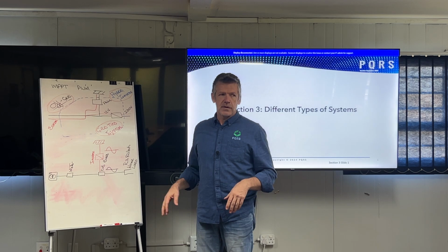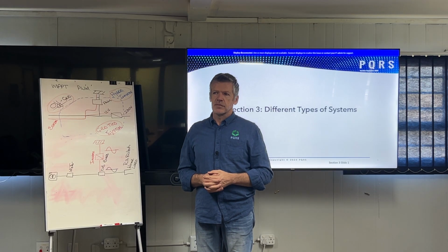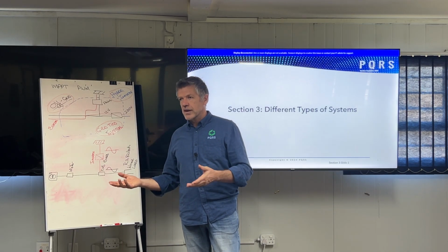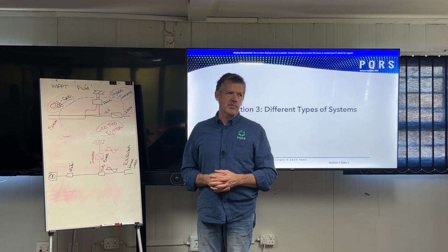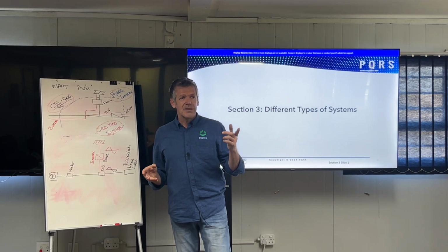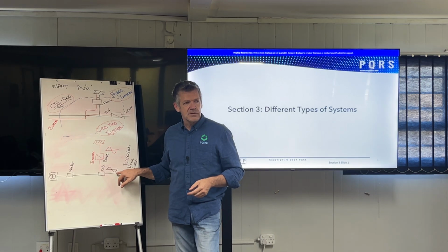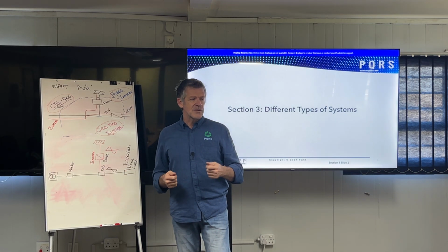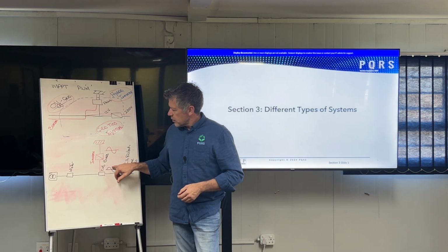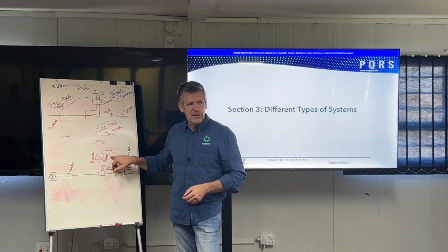Early in the morning, this inverter is sleeping before the sun comes up. The inverter falls asleep in the evening when the sun goes down, and it wakes up in the morning when the sun comes up. When this inverter wakes up, it starts looking for the signal. It wants to see what the Eskom signal looks like. As soon as it has seen what the signal looks like, it tries to copy that signal.